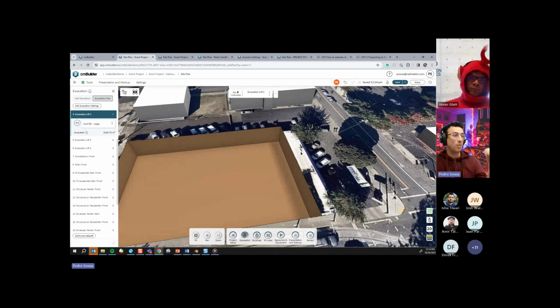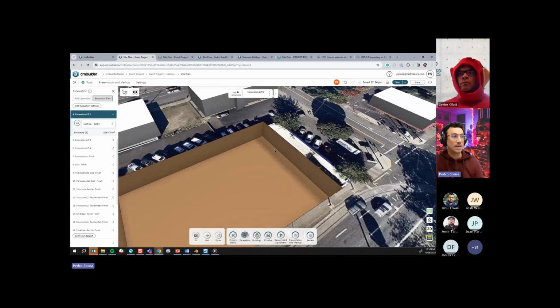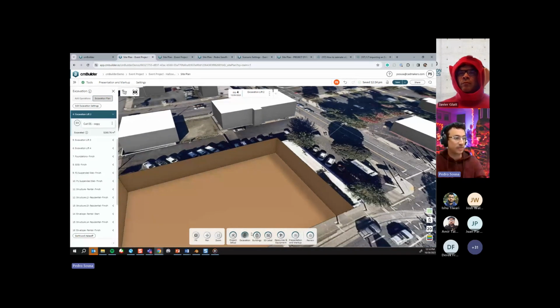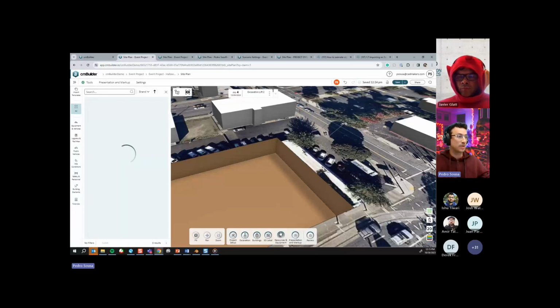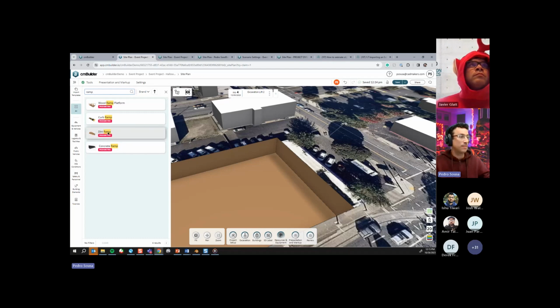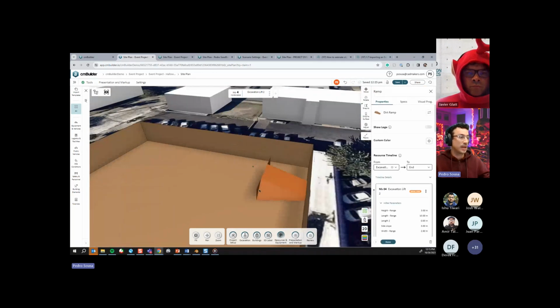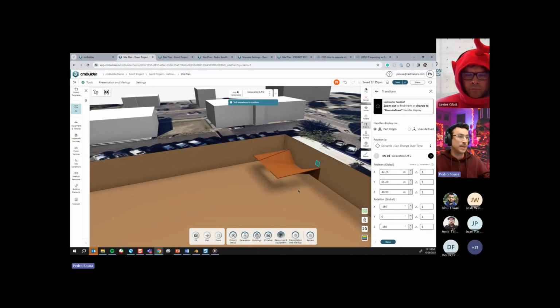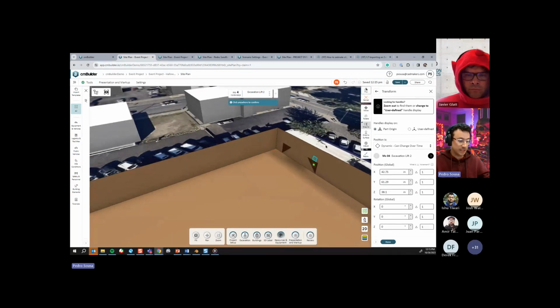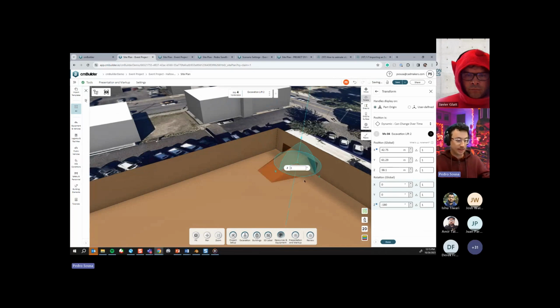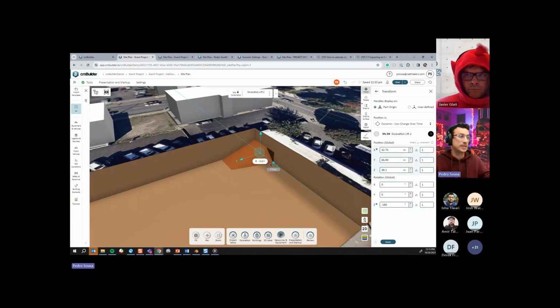So if you want to have a ramp that is located on a single spot throughout the whole excavation steps without having to add the ramp several times, you can go over here in our resource and equipment, and there is a ramp resource that you can put. It's a dirt ramp, and then you can put this one in there, and this is going to be your ramp that's going to stay there the whole time, just because this ramp is not controlled by the excavation operation.